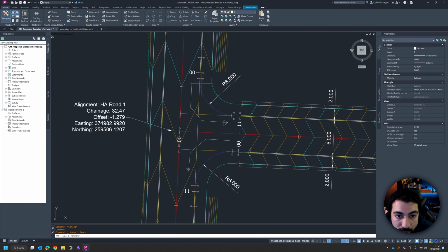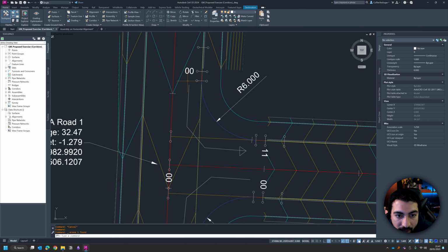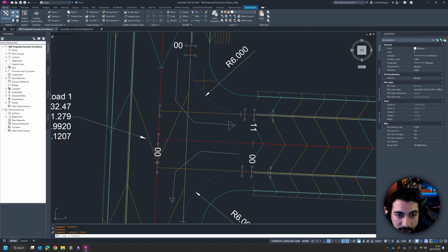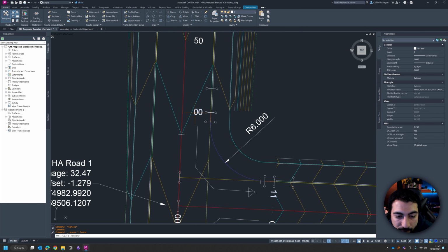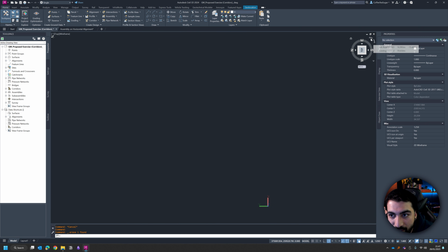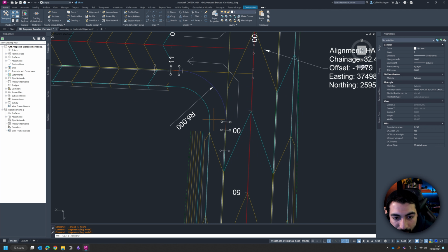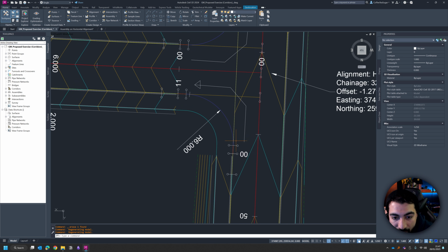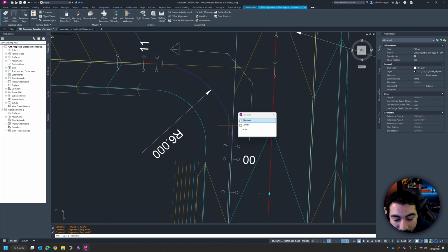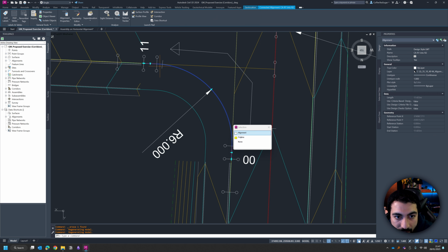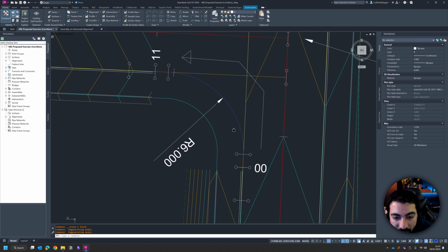The next step is to create our assembly. Because we said we're always going to do junction in and then junction out, we need to look at what we have if we drive from this side out. Let me just rotate it slightly so we can visualize it better. So we're driving in. On the left hand side we need the footpath, and on the right hand side we need the carriageway, because this is now our center point. So we're going to tell the assembly to follow this curve.